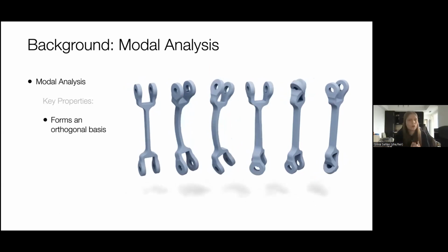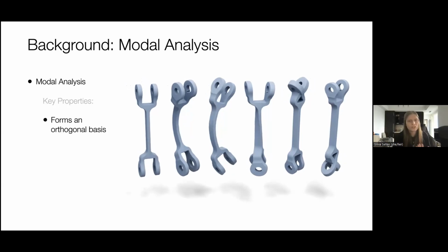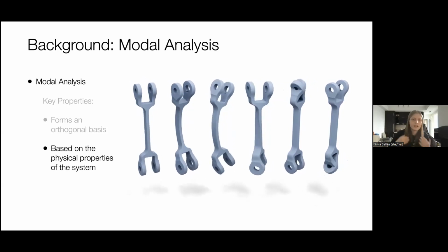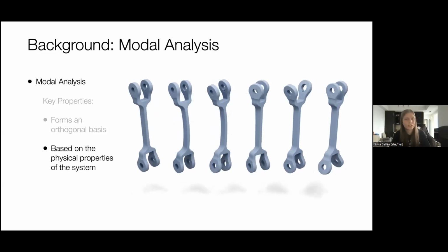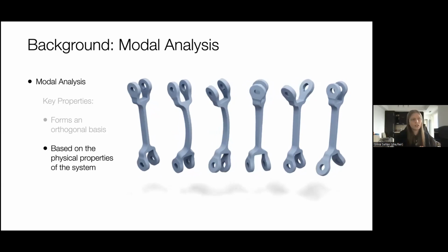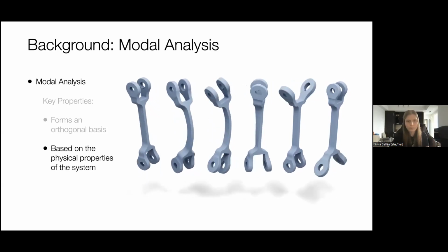The modes form an orthonormal basis, which means that any state, any deformation state, can be decomposed into a linear combination of modes. Orthogonal, meaning that energy cannot be transferred between modes, so they form a completely diverse and separated set of deformations. Modes are based on physical characteristics of a system, so this isn't just a procedural geometric algorithm, it's based on the physics of the system.